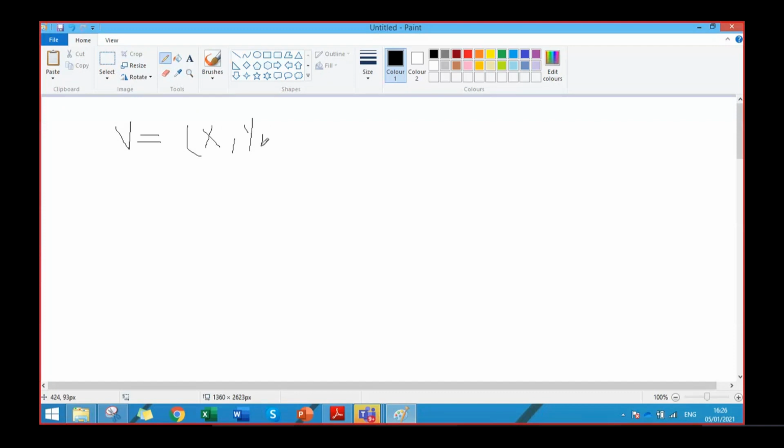It can be steady or unsteady. There can be a change in the velocity with respect to time as well. There can be a change in the velocity with respect to the location, that is the x, y, z coordinates. So there is a spatial component, and there is a time component as well. So every fluid property depends on the space coordinates and the time as well. Whenever discussing fluid properties, we need to be sure how the fluid property is varying. Is it varying with the location, or with the time, or with both? Okay, is it clear?